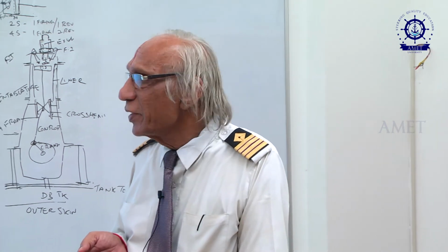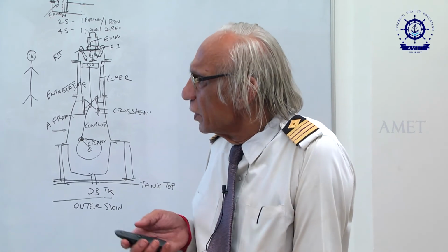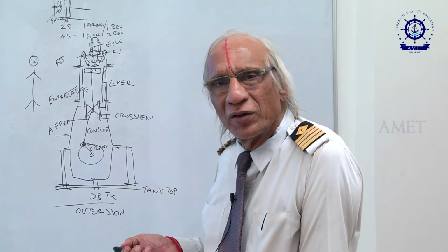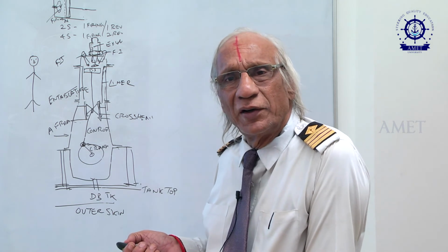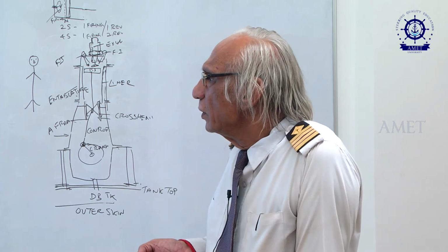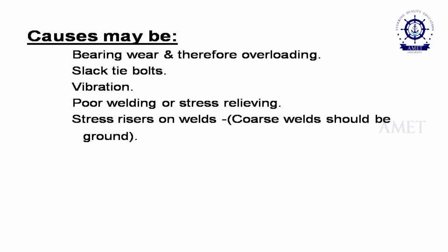And engine units are not balanced. Therefore, you may have some vibration, either engine induced vibration or propeller induced vibration. The fourth point is that the welding itself may be of poor quality, or the welding may be good but was not properly relieved of the residual stress left after welding. And there are some discontinuities in the structure, where there are changes in cross section, and all these welds have some stress risers. Coarse welds should be ground properly, otherwise they can be a point of discontinuity and provide stress raising and contribute to cracking of the weld.